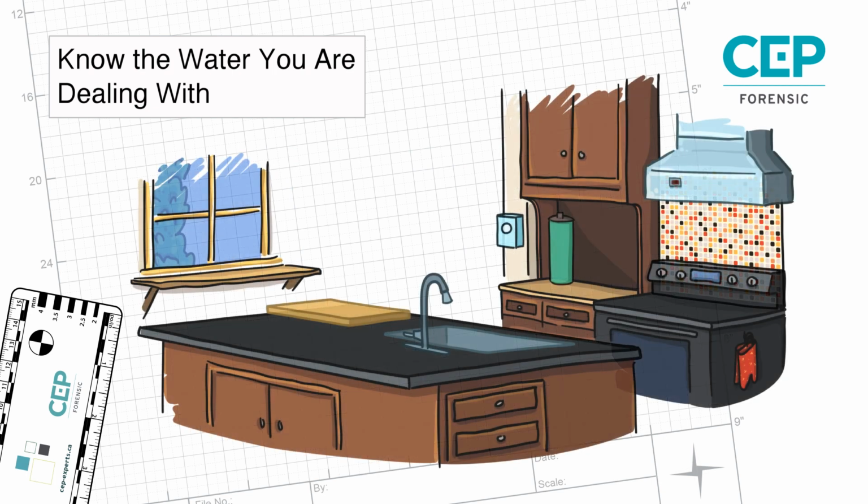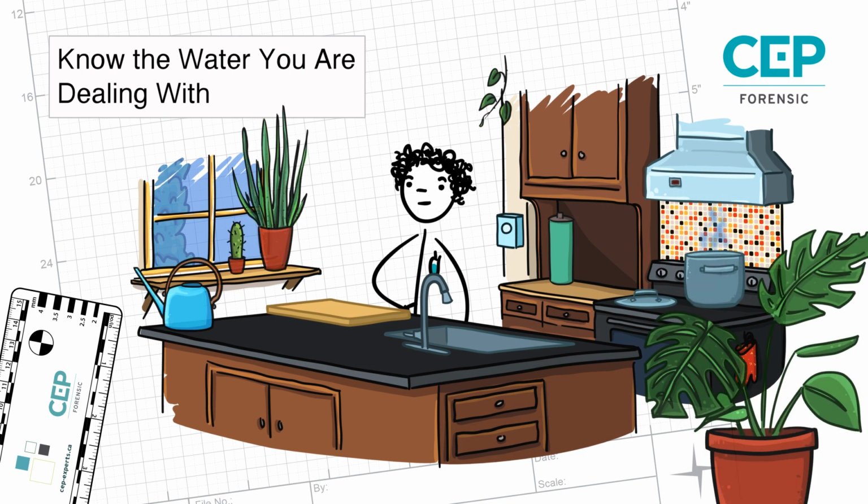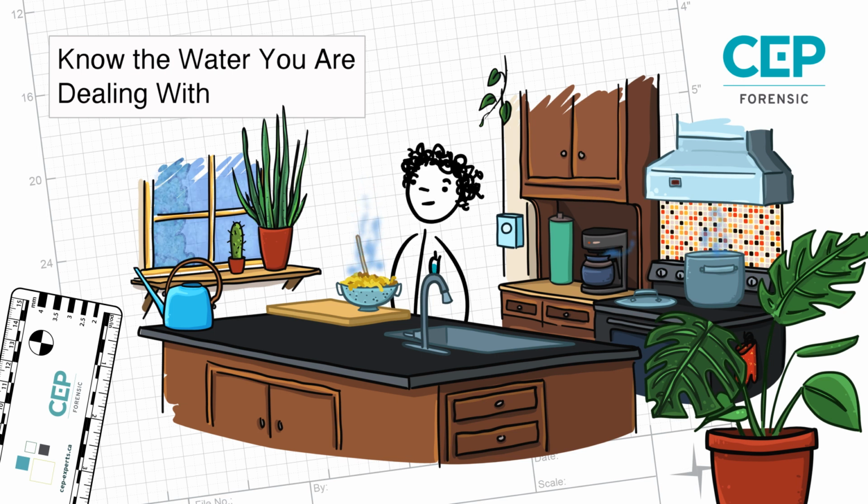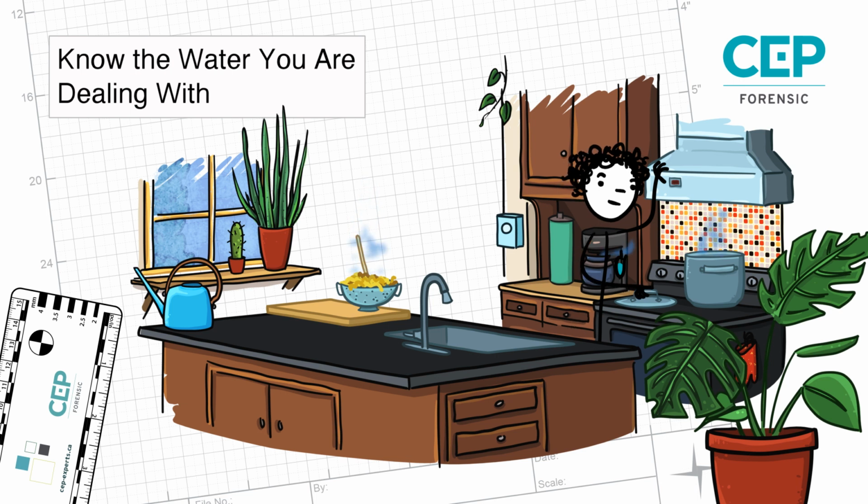Several factors can contribute to the development of condensation within a building. For example, occupancy behaviors, including cooking, breathing, watering plants, and humidifying living spaces, all increase the ambient moisture. Building systems, such as HVAC systems, when poorly maintained or inoperative, or extreme weather events like cold snaps or high outdoor humidity, can also trigger condensation. Gaps or voids in building insulation create cold spots that support condensation. But don't worry, practical solutions for these types of moisture problems exist.